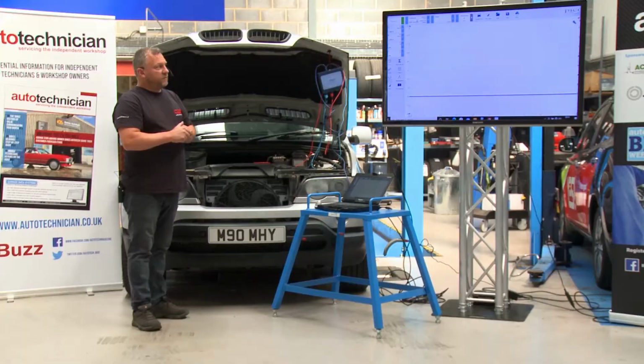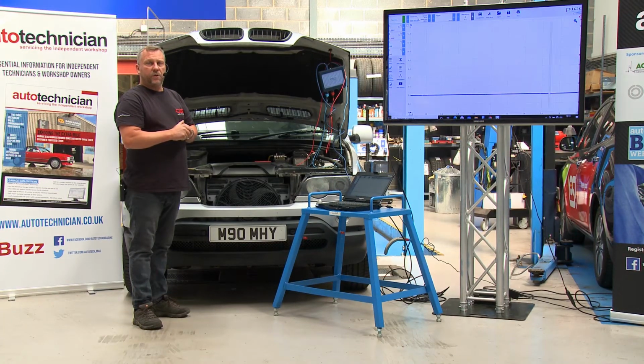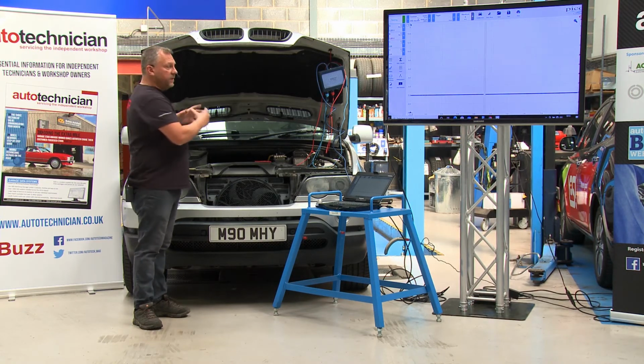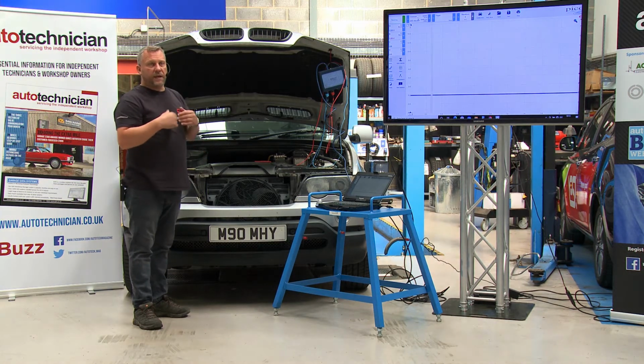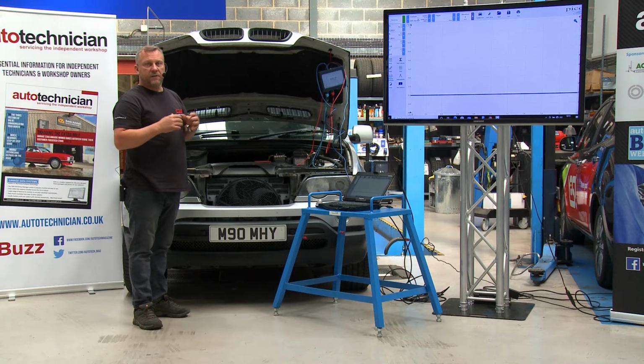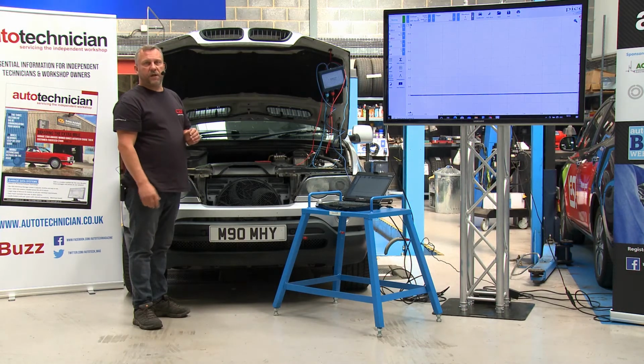The vehicle's been scanned for fault codes, and the only code currently stored is a camshaft sensor problem. The vehicle is an intermittent non-start and is currently starting. So we're going to use the camshaft sensor as our signal while we look at how we adjust time bases and use triggers to steady the image on the screen.